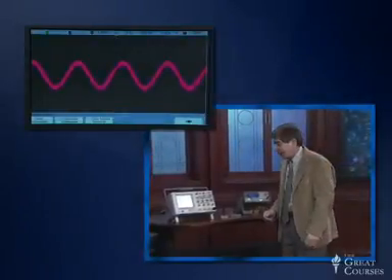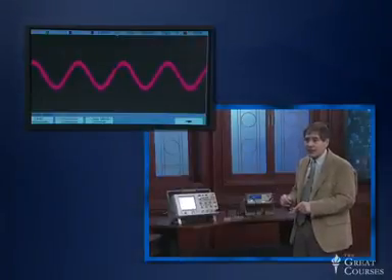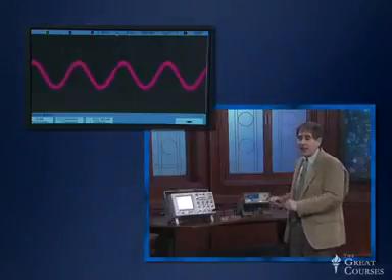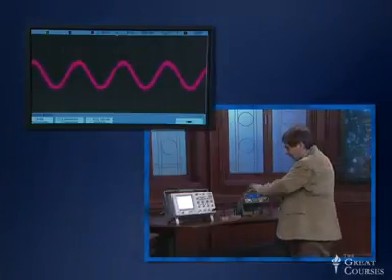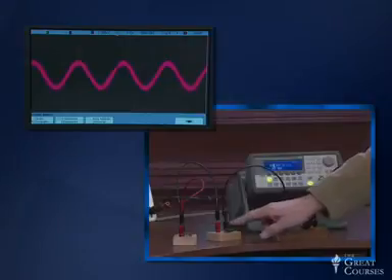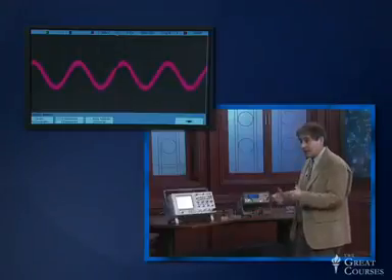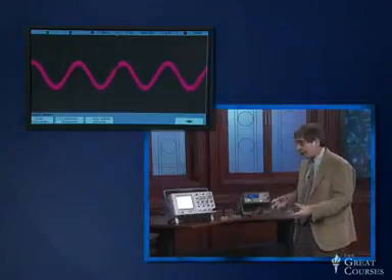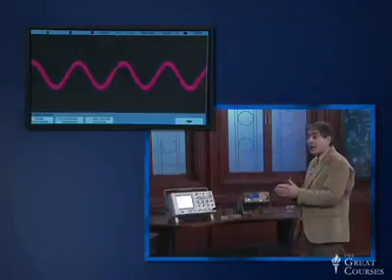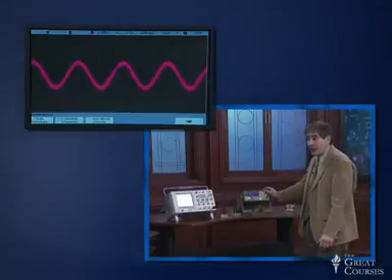And you see on the big screen and also on the oscilloscope a sine wave displayed. That is the sine wave that represents this particular waveform that I'm generating here. As always, we have an awful lot of noise in this studio, so that sine wave doesn't look nearly as clean as it ought to. I'm also not taking precautions and shielding my wires like I should. Now, what I have here is an inductor, a capacitor, and a resistor. The values of the inductance and capacitance are chosen so that the resonant frequency, the natural frequency this circuit wants to go at, the frequency at which the effects of the capacitor and inductor cancel each other out, is somewhere in this range that makes it reasonable to start at 800 kilohertz. So now I'm going to bring the frequency up.